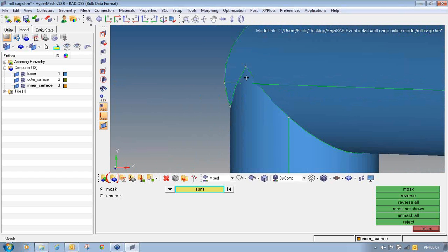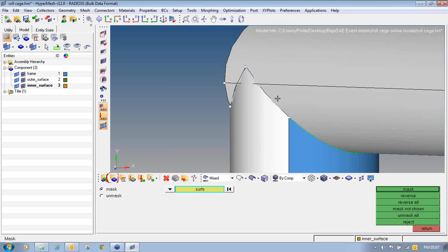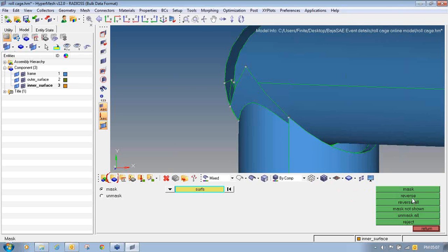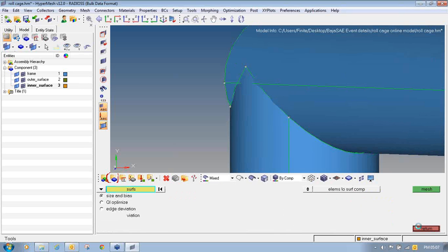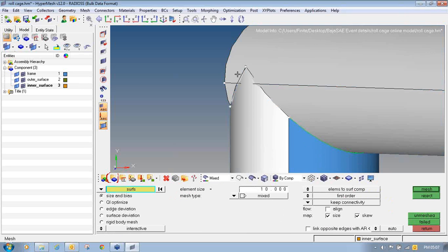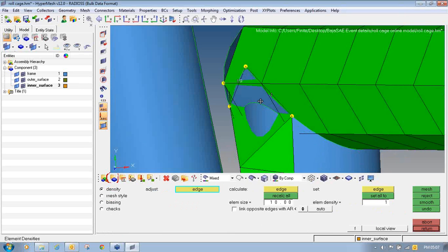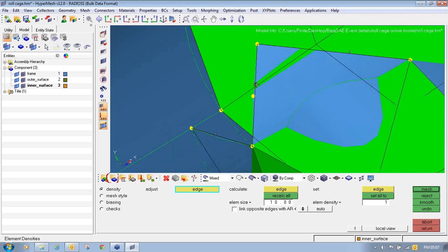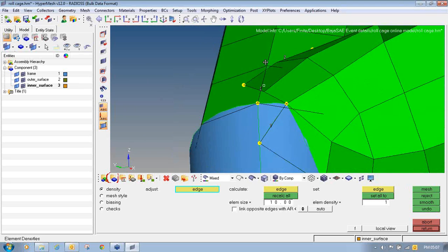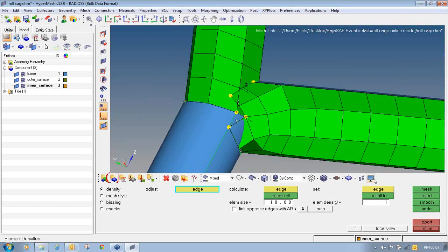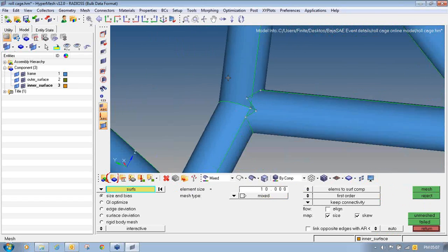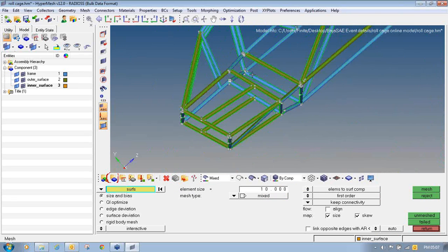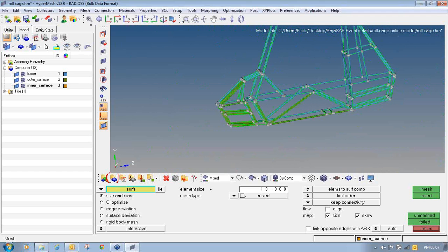You can see there is an overlapping. Once you go for meshing of these two, the meshing will overlap. If I go to mesh this surface in 2D itself, you can see the meshing is overlapping. I can change the number of nodes here. So these are not properly connected. That's why we will first divide the surfaces and then move them.